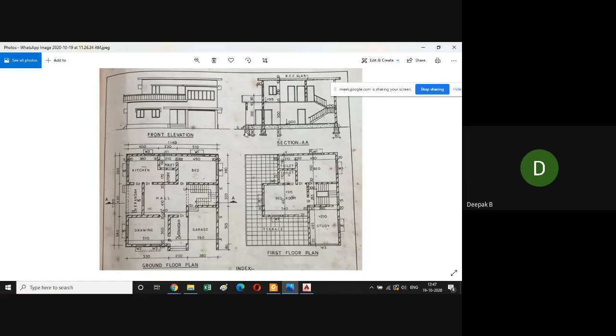As explained in the previous class, below each wall you will have the plinth foundation and the proper ground foundation here, and beneath that you will also have a layer of PCC. Okay, the dimensions you can assume here, mostly it will be 30. You can assume 50 here for the lower foundation and 80 for the PCC layer.